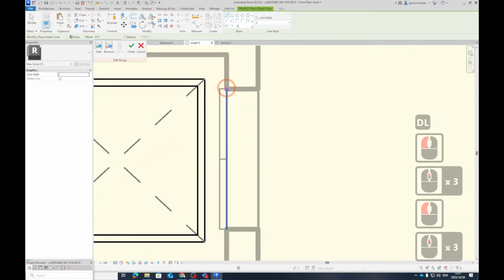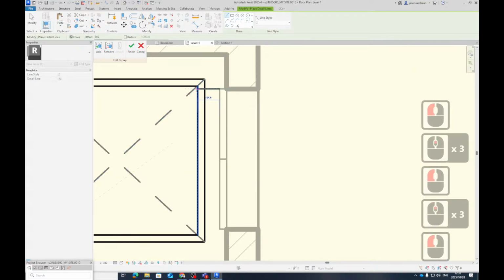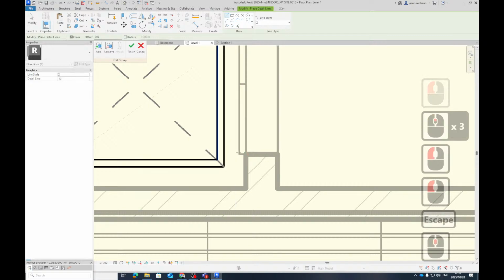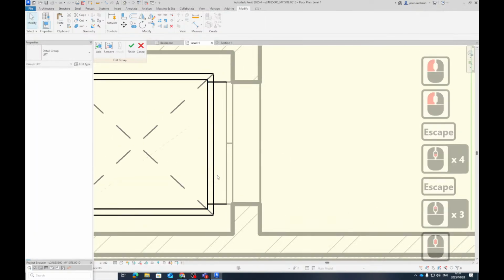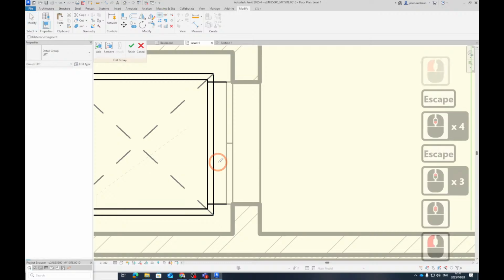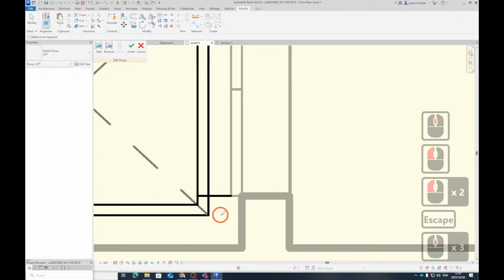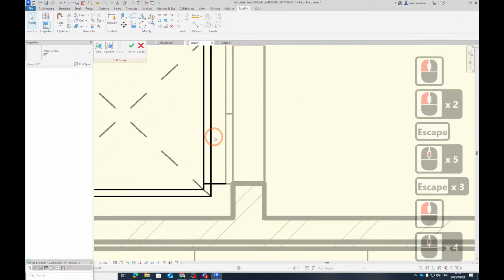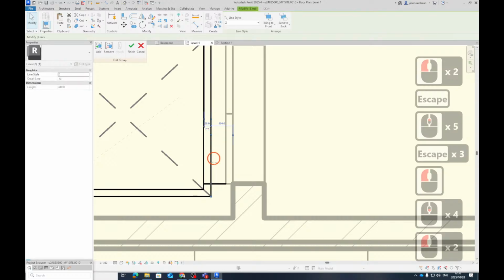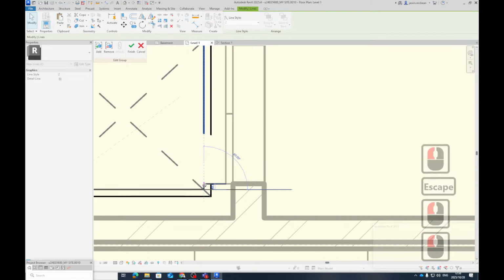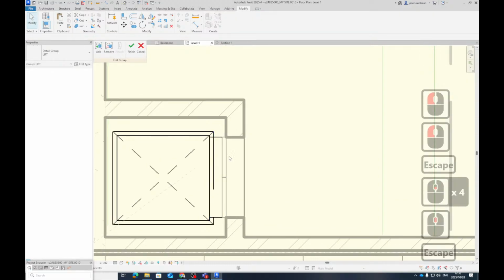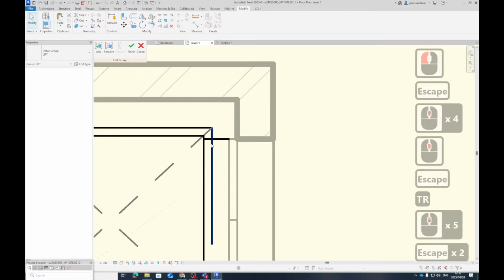If you don't know what the thing is, so if I draw that to there to make it look like it, you'll see this is quite cool. And then maybe I want to trim this line work, so split lines. So you just make your own components. If you don't have it, we draft it, we draw it. Okay. The problem with Revit, some families are so complex, it'll take you longer to model the family than your whole building because it's so complex.